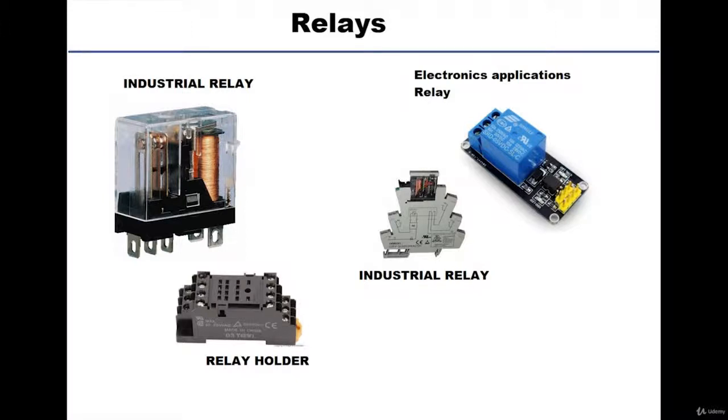Another really useful application is when we have a side of the electrical panel that is specified for button control and switch controls. Not all the time do you want to use the PLC. Sometimes if the PLC is down, you still need to control your equipment. So there is a part in the electrical panels that is sometimes designed, called the MCC, that fulfills this job, using relays to do this control operation.